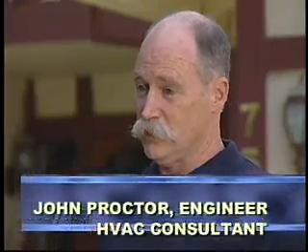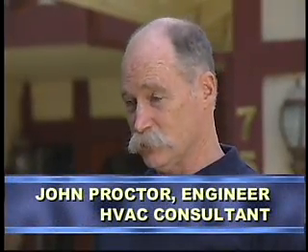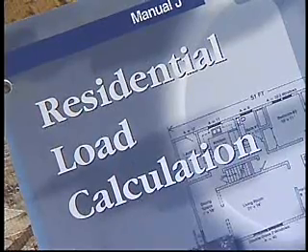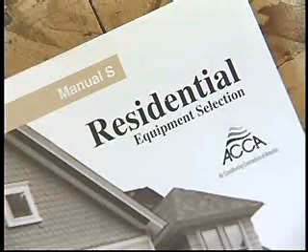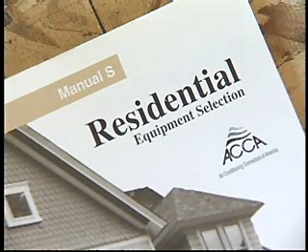Well, the first thing that they should insist on is to get a load calculation. They have to know that the contractor had sat down, figured out how much window area there was, what kind of windows they are, whether or not they're shaded or not. And from that, they need to calculate what the real size air conditioner is that they need. It's a very standard method of doing that. It's ACCA Manual J, and getting the right size air conditioner is ACCA Manual S. And they should insist that for every single house that they build, the AC contractor provides that information to them.